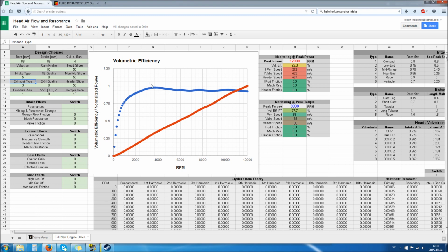So if you are at too low speeds, then the resonances won't work either, because they were created by air rushing onto the closed inlet valve after it has closed, and then bouncing back and forth. But if you're just coming there with like 10 kilometers an hour of airspeed, there will be basically no bounce, so you will have no resonances. So this also acts not only as a mixing modifier, but also as a modifier for the strength of your various intake resonances.